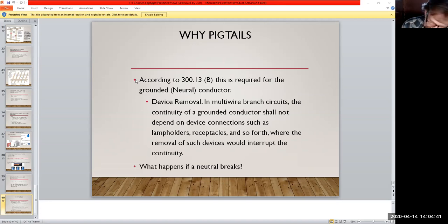I hate non-electricians that do electrical work, but you'll see it from time to time in junction boxes, or primarily in connections, like just receptacles and switches. So let's say you have a couple wires coming in, okay? You're going to join them together and have a wire nut or whatnot on it, okay? But now some people will literally use the receptacle as the junction, right? So they'll have these couple of wires hooked up to it, and it's like, no, no, no.